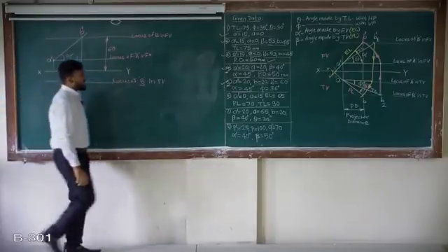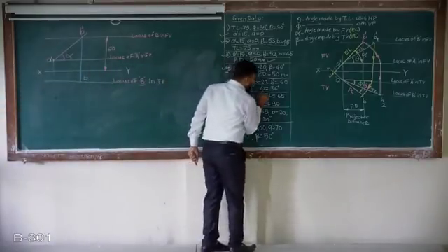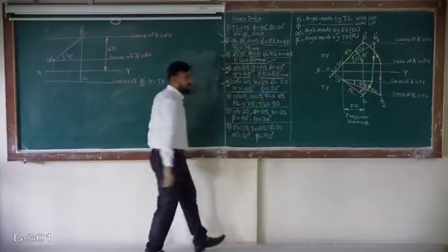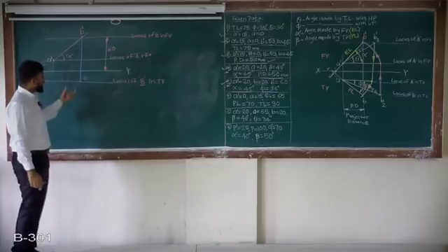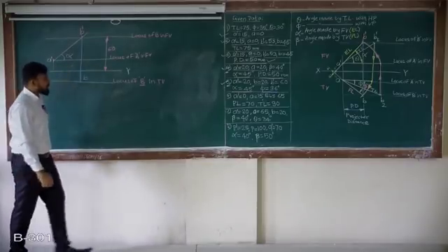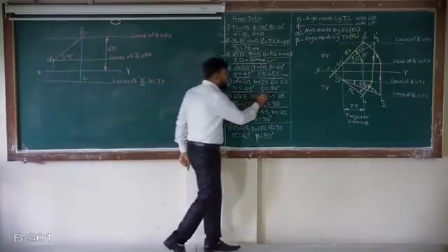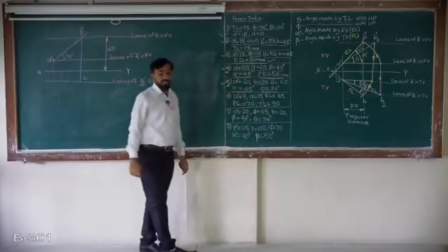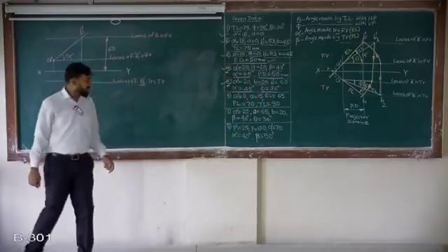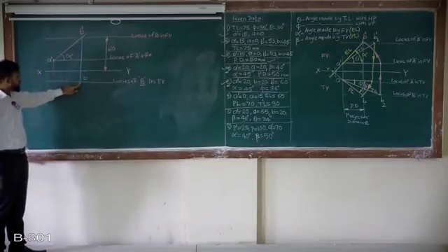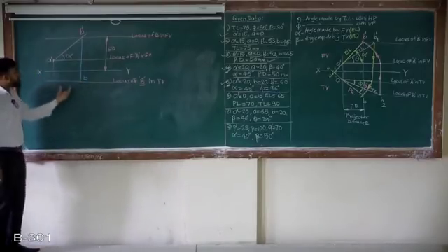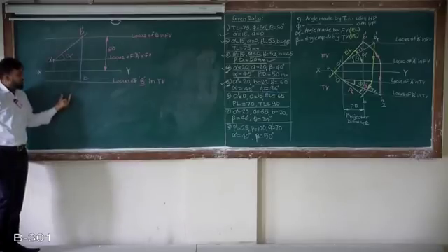Now the angle is given, that is, the angle in top view, the angle made by the line with the VP. So how to get the true length? Remember, this phi is the angle made by the true length of the line, and the point we get here is B. To get a point from this, which parameter should we have?